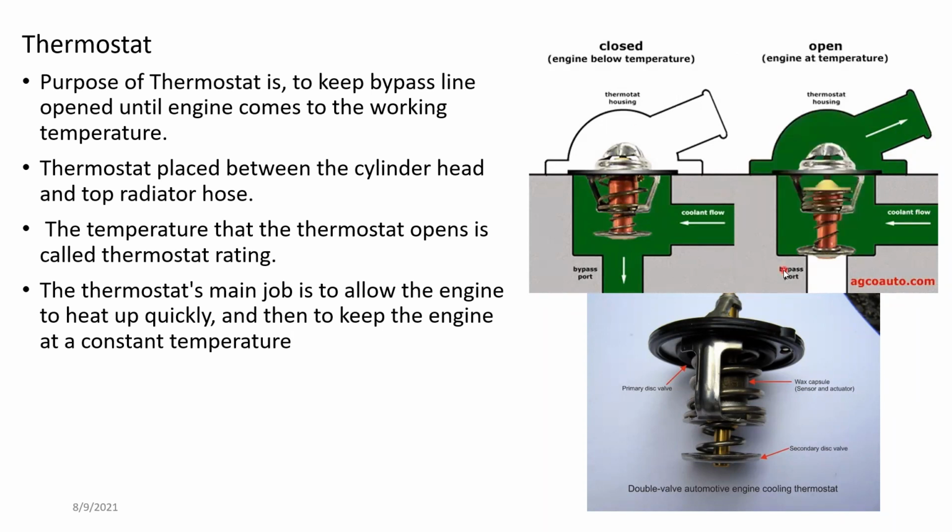So it's not possible to change thermostat valves with another engine, because each engine's operating temperature is somewhat different, within about 5 degrees. Unless it's exactly the same, it can't be swapped. So thermostat valves should not be changed.